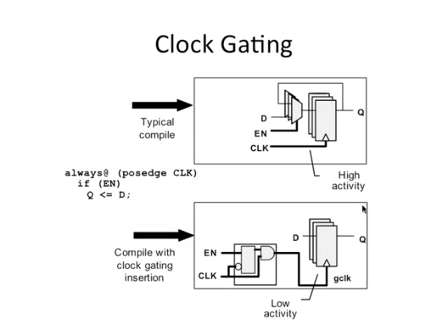What is interesting is that clock gating helps to reduce area also for this kind of structure, because in a non-clock gated structure, I have so many muxes. Every input has a mux, so there are 32 muxes if it's a 32-bit bus, whereas here there is a single clock gate and I am removing those 32 muxes. So it also helps to reduce the area of the structure.